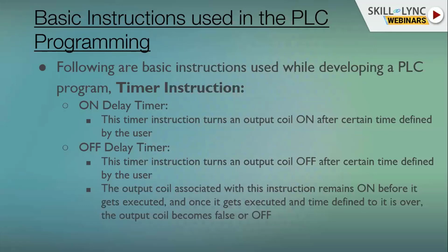Like that, there is the off delay timer, which is just the opposite of the on delay timer, where the output connected with the timer remains on in the beginning. After the timer runs and the time is up, the output will be off.